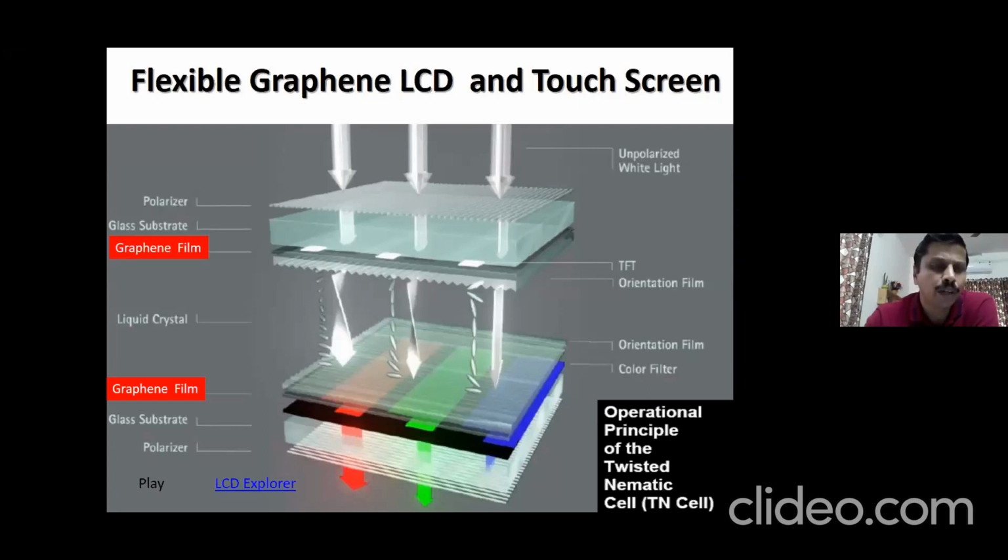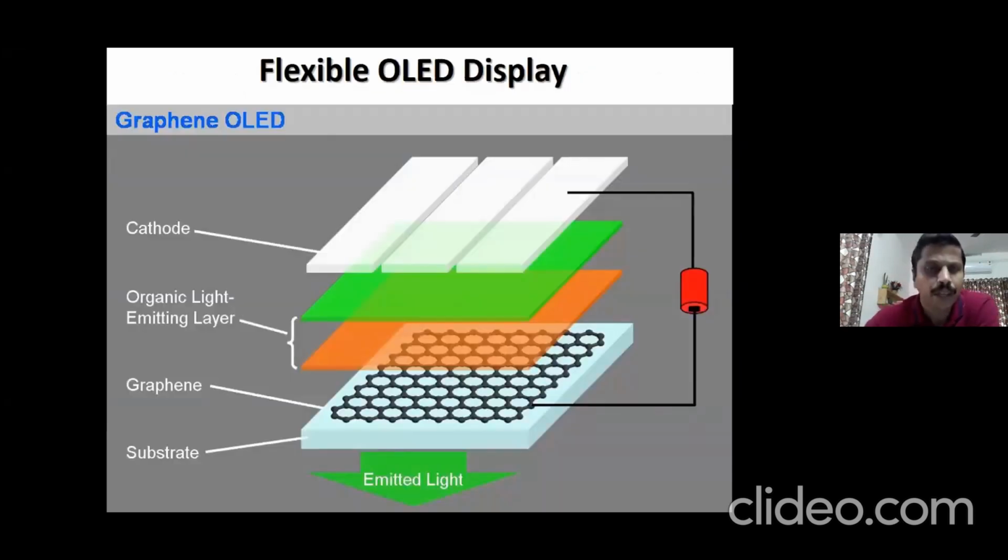The top electrode and bottom electrode, currently we are using ITO, indium tin oxide, but you can use graphene. That will be a revolutionized technique. Especially since graphene has very good optical transparency, it can give better image, right? So that is one interesting area we can think about.